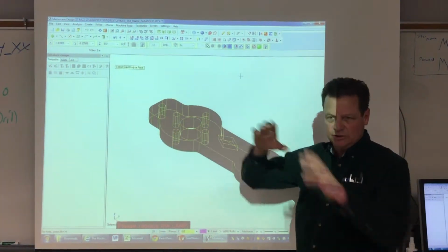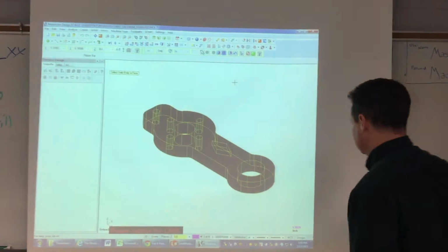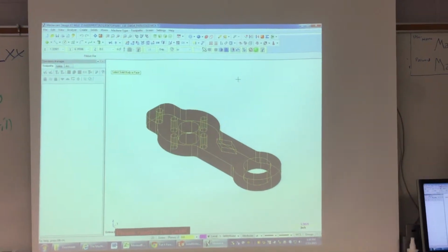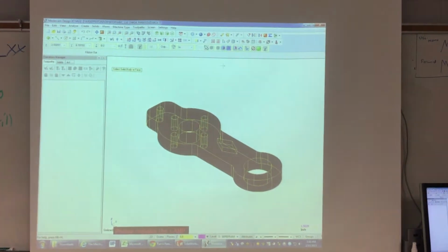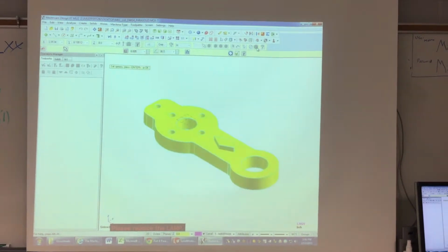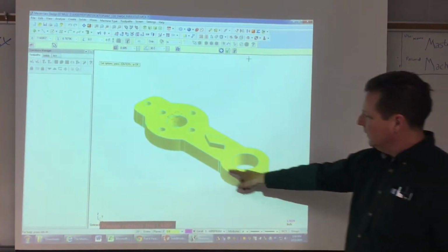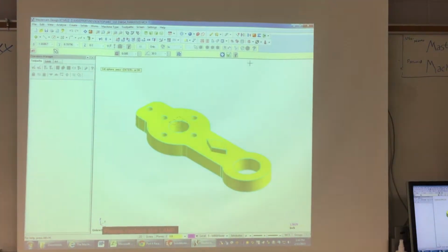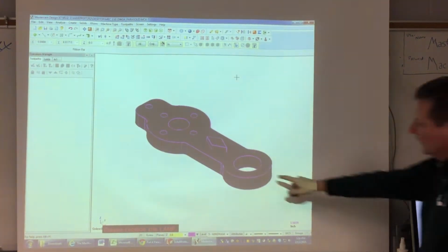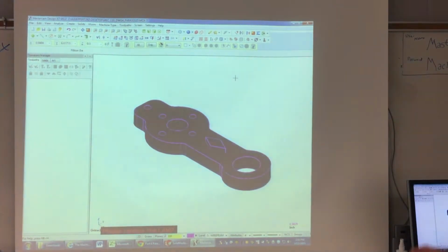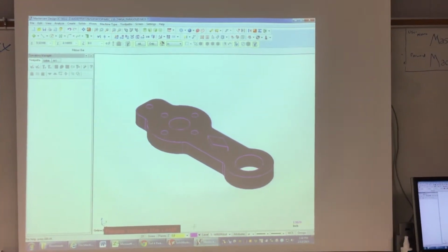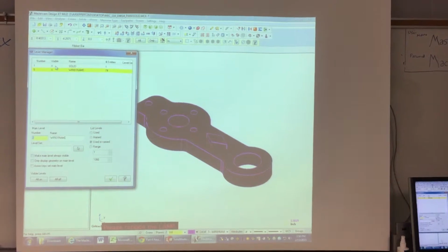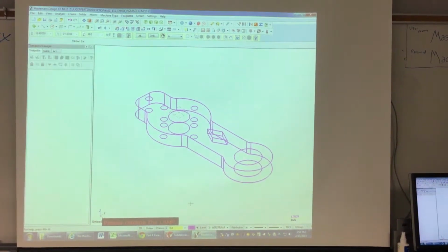Not surfaces, just edges. So it makes lines and arcs and things like that. It doesn't make surfaces. When I finish selecting, you can see it lit all the edges up, and I'm just going to go ahead and green check now because it put nice purple edges all over my black model. I go back to my Levels Manager and I turn off solid.